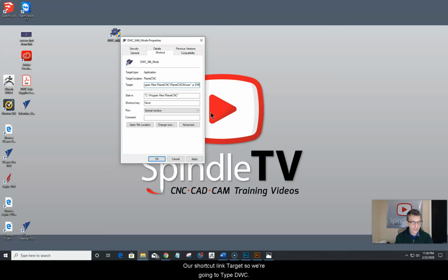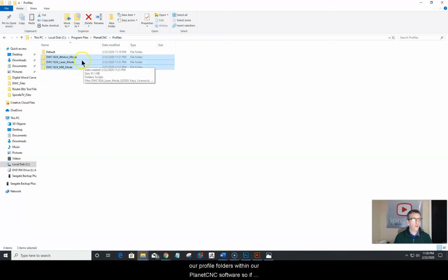So we're going to type DWC 1824 underscore mill underscore mode. Now this name here, this DWC 1824 mill mode, is the name that needs to match exactly our profile folders within our PlanetCNC software. If you'll notice here, my mill mode is DWC 1824 underscore mill with a capital M underscore mode with a capital M. So that's the target. That's what that icon, that shortcut, is going to be pointing to. So it has to have the same exact name.